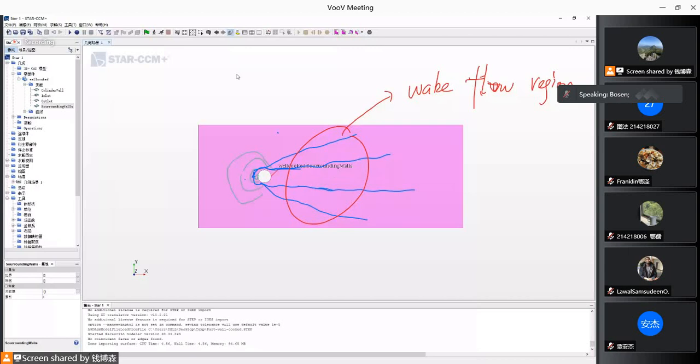Okay, so what will happen in the end if I move the cylinder towards the downstream region, for example, in the center, is that I will waste some of the areas. For example, I will waste the computational areas in here because they all belong to uniform flow. This area would be somewhat wasted. It's a waste of my computational resource.